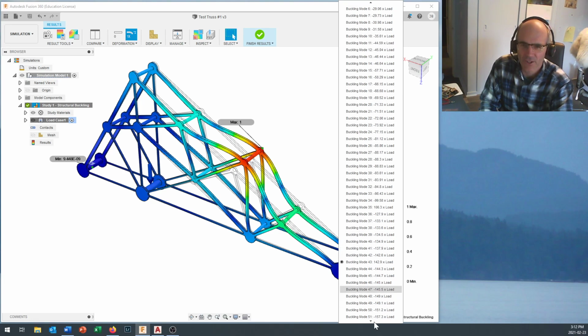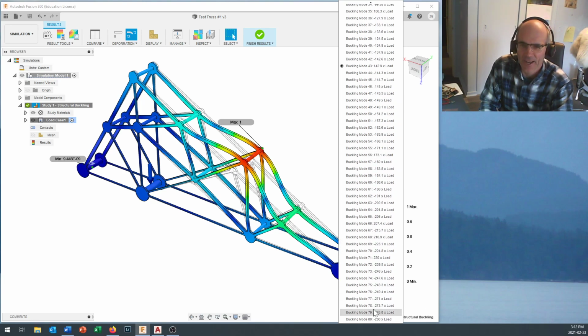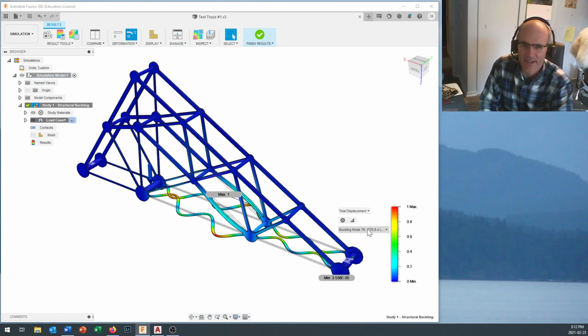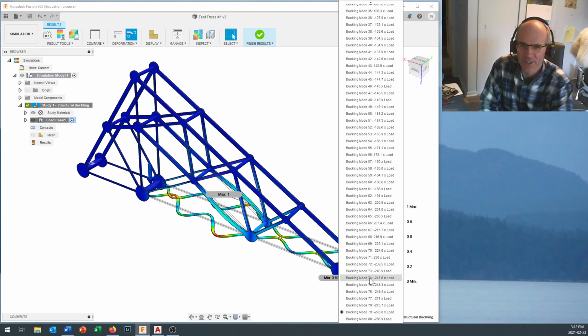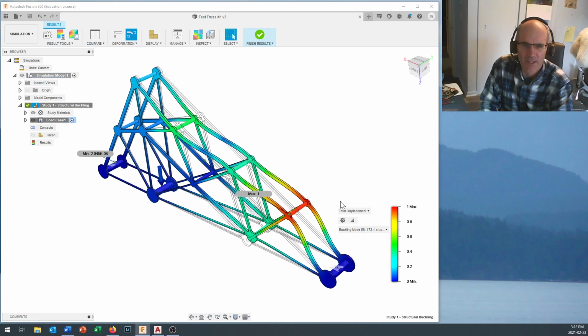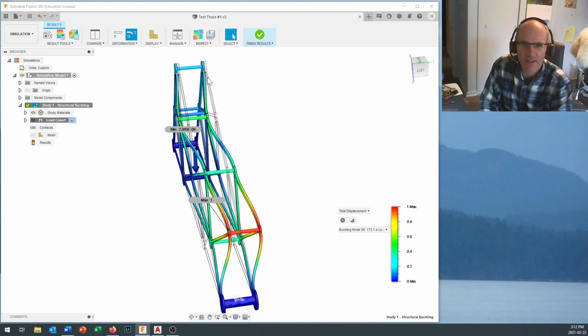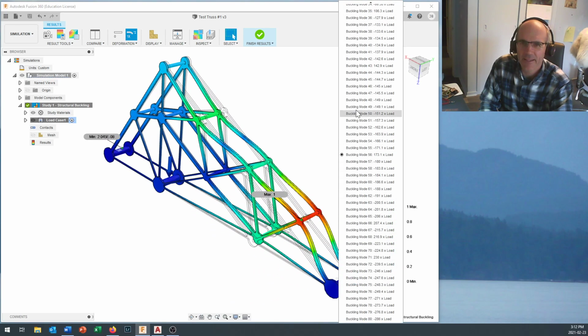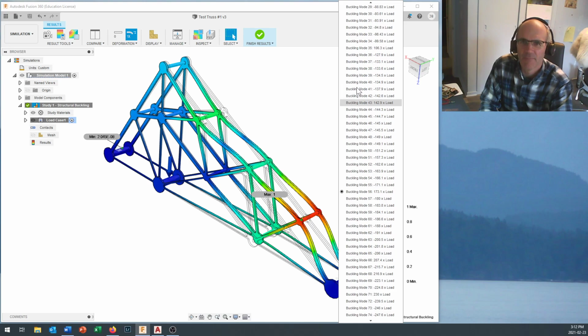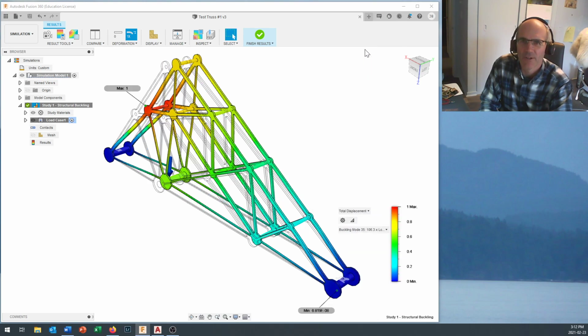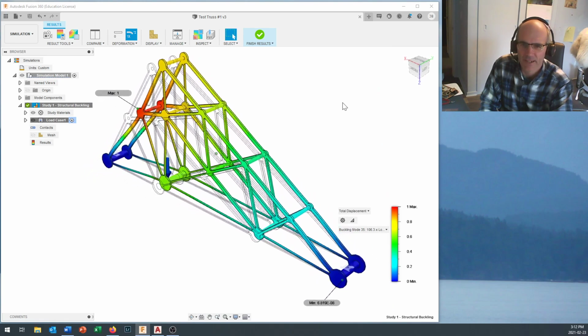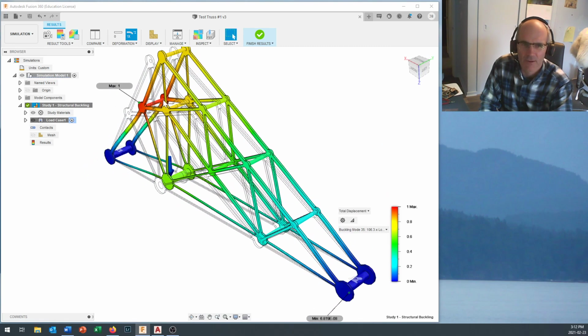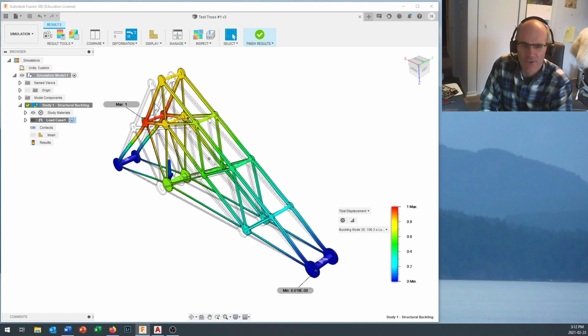As you go further into the structure, I asked for 80 calculations, and there's a negative response. Some of them are just silly. Like I say, garbage in, garbage out. If you were ever able to get up to 173, this is another buckling mode that could affect this member coming right down there. But again, anything past your first buckling mode right here at 106 is mostly for entertainment value, okay? Because this structure is going to pop out to this side due to a failure in the back right there. We need to do something about that before we go on.